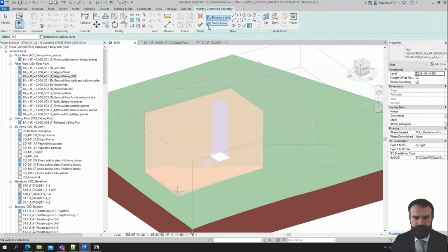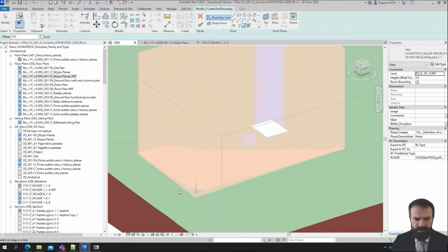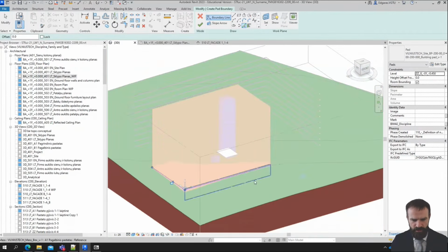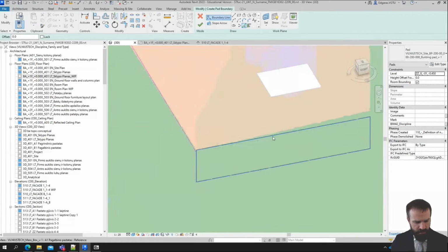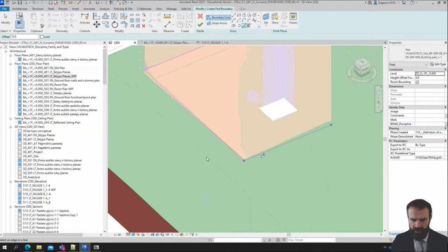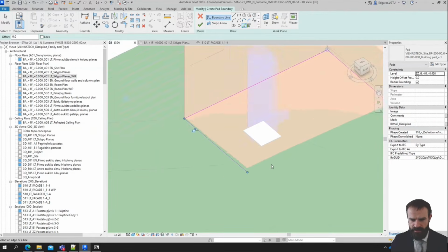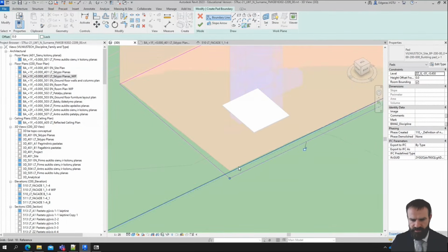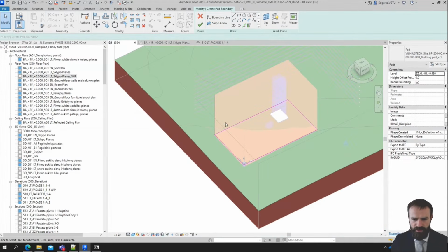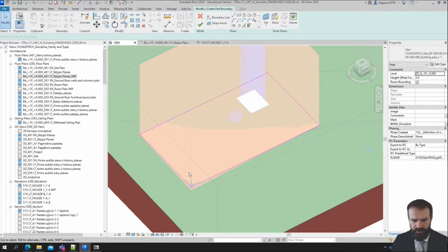And now let's try to activate building pad again. It works nicely. So I select pick line tool, and this tool lets me select object faces, and I can go around my building by clicking shift and mouse wheel. I can rotate, and here I can select faces of my mass object, and now I have a nice closed loop rectangle representing my building outside part.